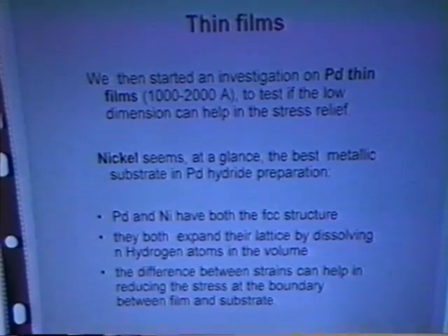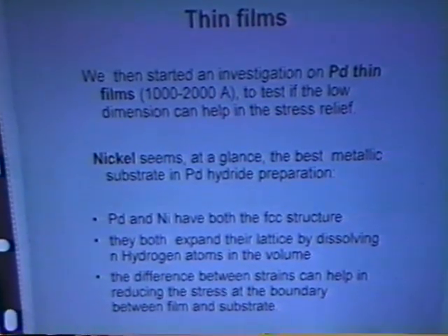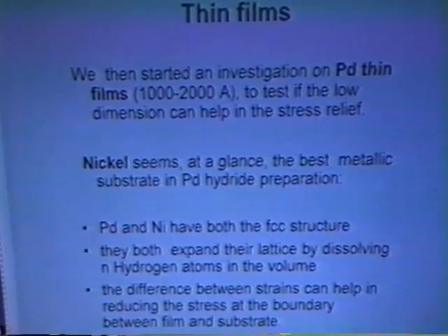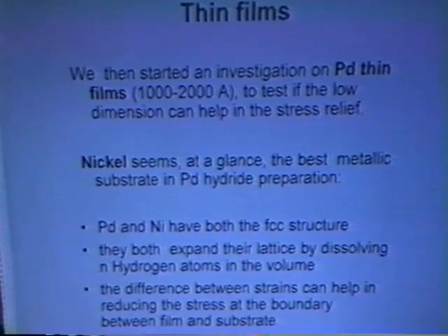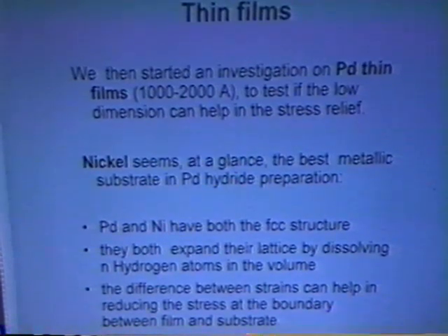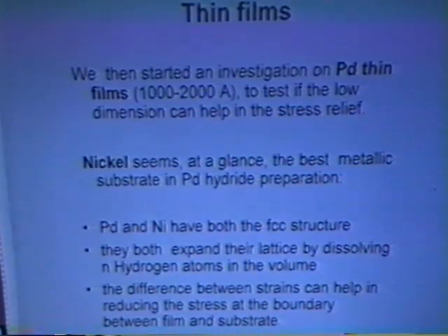Palladium and nickel have the same lattice structure. They are both FCC structure. They have almost the same lattice parameters, which allows epitaxial growth on the surface. They both expand their lattice by dissolving hydrogen inside. And we hope that the difference between the strains can help in reducing stress at the boundary between the film and the substrate.